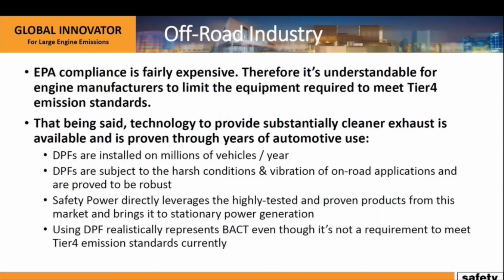And Safety Power leverages this existing, highly tested technology. I don't know if you know this, but the DPFs that we use in our systems, for example, are actually the exact same DPF canisters that are used in the on-road trucking industry. So we're just basically taking that technology and applying it to off-road, leveraging the experience there, and it also makes it very easy to clean when required because the infrastructure already exists. So DPF realistically represents what is the best available control technology.